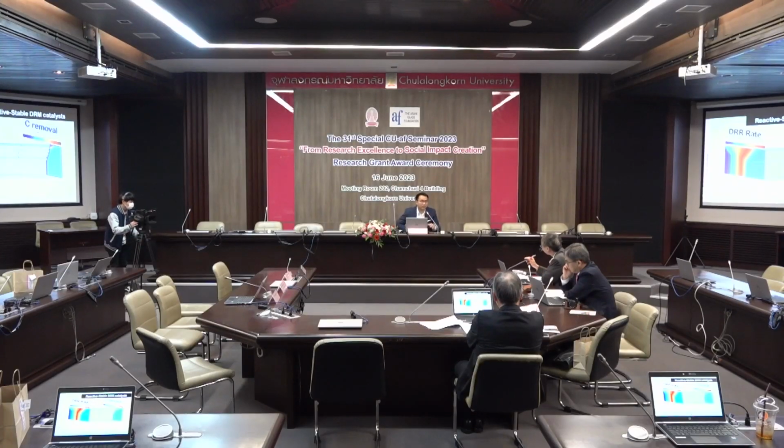So for that, as you say, that one is called sintering, right? The agglomeration of the active site. So in that part, typically what they do is redistribute the active site again. It's already aggregated and you cannot just separate it. So you can do many things, like make it oxide form again to let the oxygen separate the active site, and then you reduce it later. So you have the separated small active sites again instead of the big one.